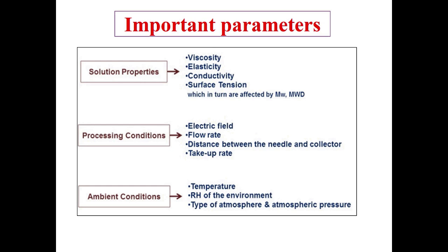Solution properties. When we talk about the solution properties, as I mentioned, viscosity is one of the most important criteria. When viscosity is moderate, then alignment and drawing of the fiber is uniform without any formation of knots. When moderate viscosity is there, it has good elasticity. Elasticity is the property of the material which has the ability to elongate during the drawing. Conductivity is very much important. Surface tension is one of the important parameters, which is affected by molecular weight and molecular weight distribution.